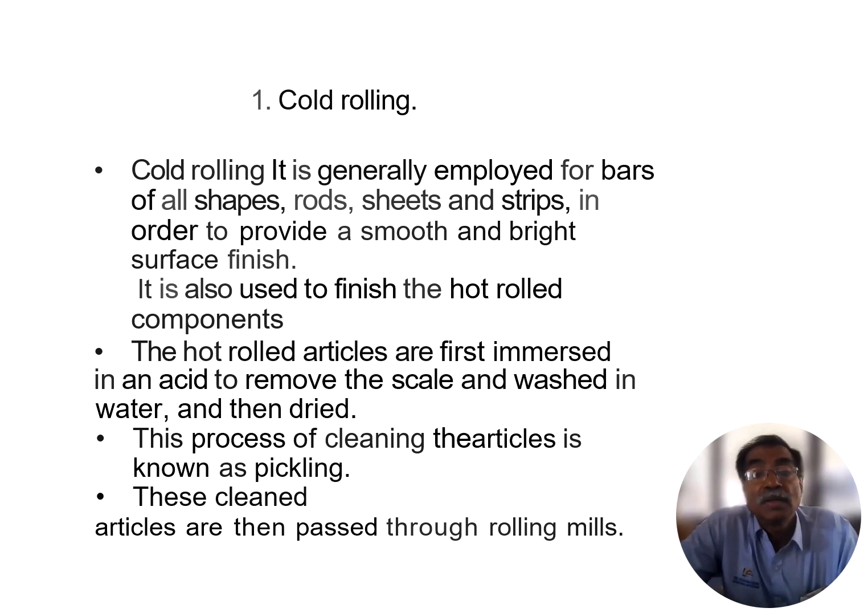The hot rolled articles are first immersed in an acid to remove the scale, washed in water, then dried. The process of cleaning these articles is called pickling. These cleaned articles are then passed through rolling mills.